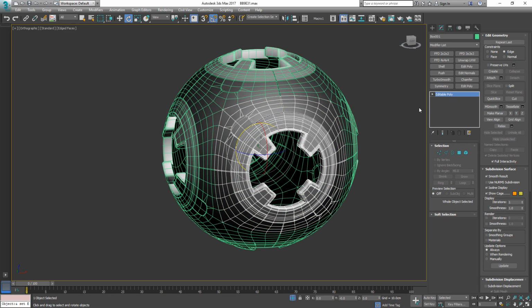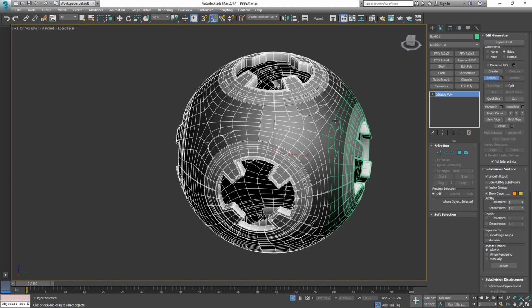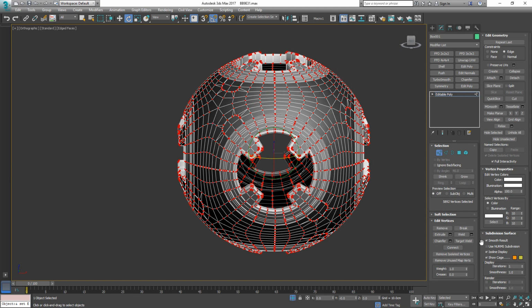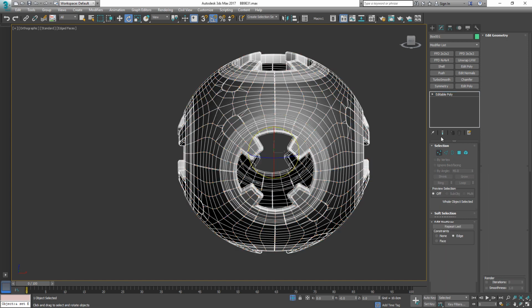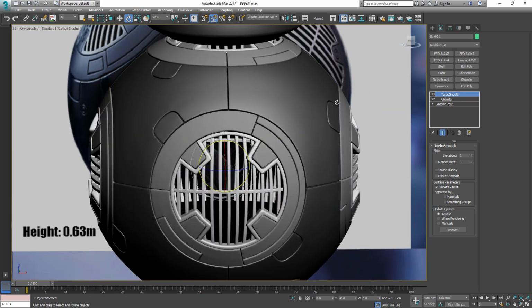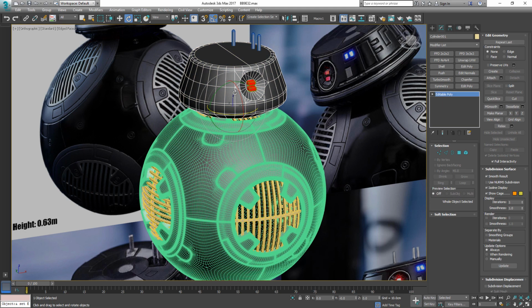And now let's just select one, go to attach, and let's make sure that they are all attached together here. Before we switch here to our vertex mode, like right now, and weld it, and I have it at 0.01 once again. And with our modifiers back on here, we have now solved that problem here with this nice element being all round as it should be.